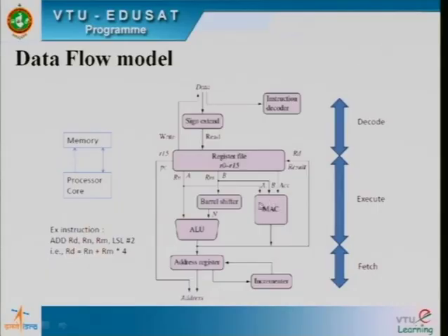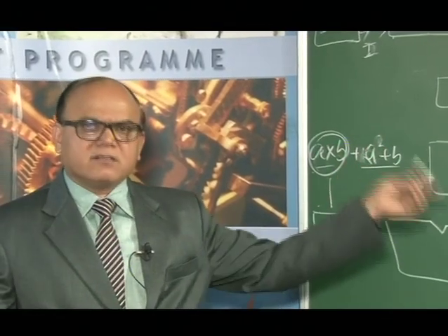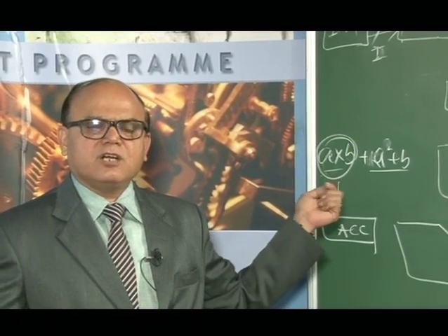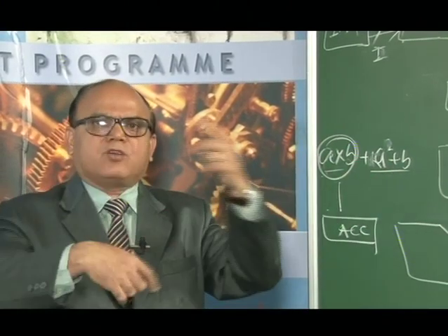For this, of course, specialized instructions are available in the ARM instruction set, and such an instruction set makes the programmer's job simpler, and the accumulation becomes quite easy. Otherwise I would have to do the multiplication using one instruction and the addition using another, and then put them in a loop.